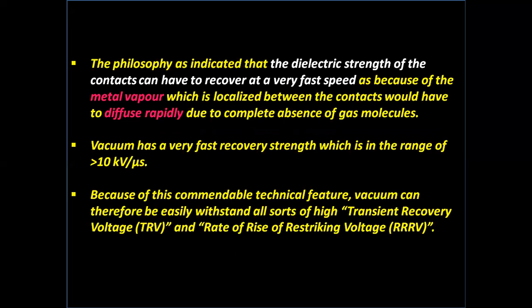Vacuum has a very fast recovery strength, in the range of more than 10 kV per microsecond. Because of this commendable technical feature, vacuum can easily withstand all sorts of high transient recovery voltage and rate of rise of restriking voltage.